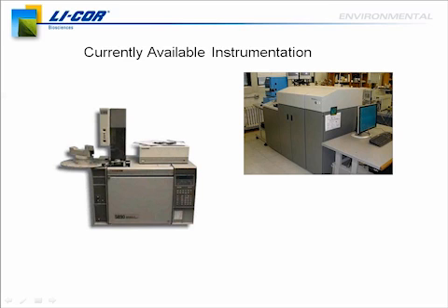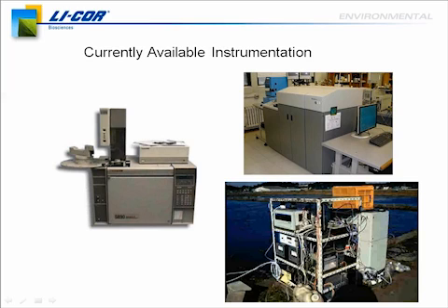More recently, closed-path gas analyzers have become available that can be taken into the field and deployed, and that allows you to get more regular data collection, and it allows you to collect that data with a little bit less time, so you don't have to go out and collect those samples as frequently. But the instruments that have been available to date tend to be really designed for laboratory use, and you can use them in the field, but it can be relatively difficult to get everything put together and to maintain those instruments for use in the field. They tend to be expensive and just kind of difficult and cumbersome for field research.